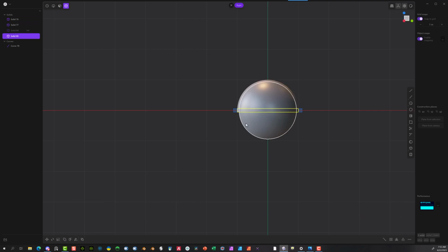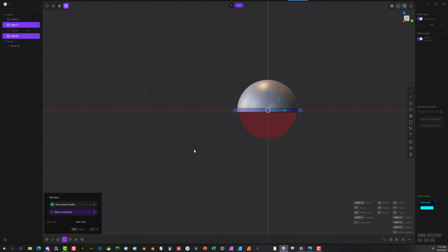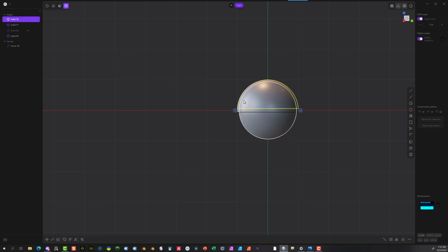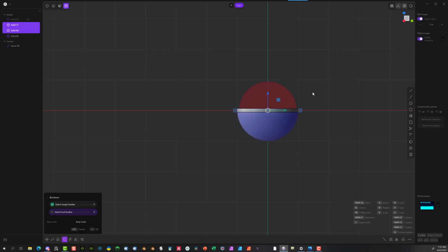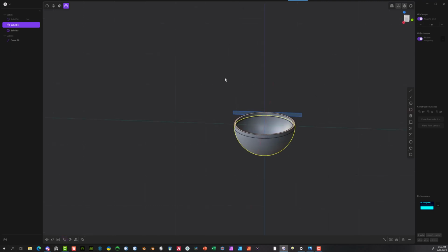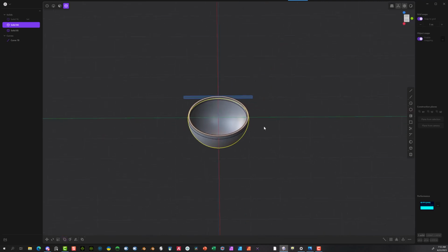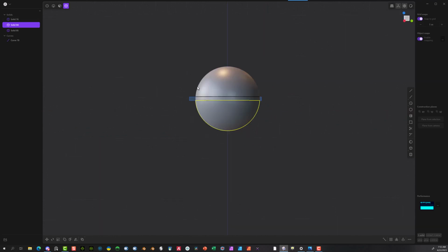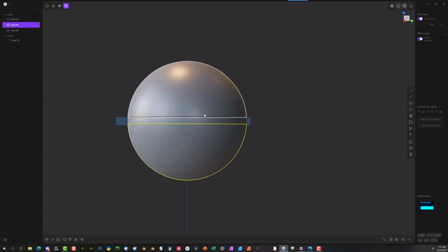Hit the center section now. Now hit the smaller sphere. Again, hit Q and go ahead and keep tool, say OK. So now you can actually hide this one on top, and you can actually unhide this bottom section. So select this. Now hit again the sphere, hit Q again, and this time you just say OK. Okay, so basically what we've done here is we cut everything through, including the top. And that's the objective, is to get it to look like that.